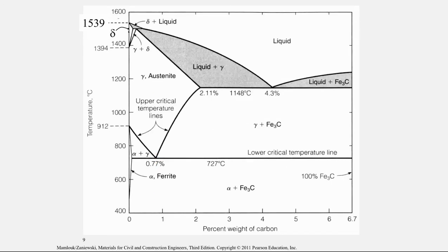Now, some more things about the phase diagram we will use to understand steel. We still have a liquidus. We have our solidus. We have our eutectic point, where we transition from liquid to 100% solid. But now we also have our two eutectoids, and these are the points where we transition the upper eutectoid from high temperature ferrite to austenite, and then the crystal structure changes at our lower eutectoid down to our low temperature ferrite. We also have the solubility limits.